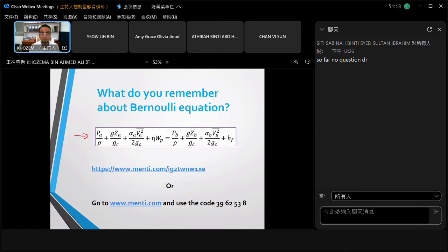So the final summary we can say is that whatever you have learned with Dr. Halina is very important. If you don't remember, please take some time and do some revision. And out of all the things that you have learned with Dr. Halina, everything is important. But the most important and the most frequent equation that we will use is your Bernoulli equation. Okay, so this Bernoulli equation is specific for pump design because we have already incorporated the pump work. WP here is the pump work term in this Bernoulli equation.